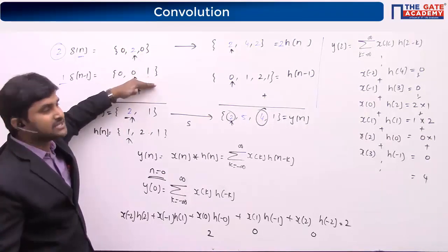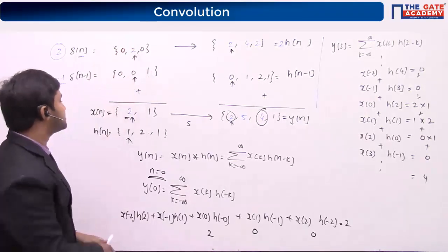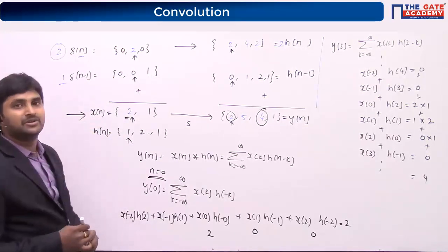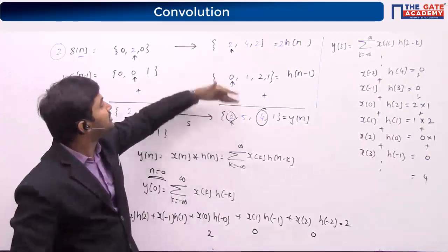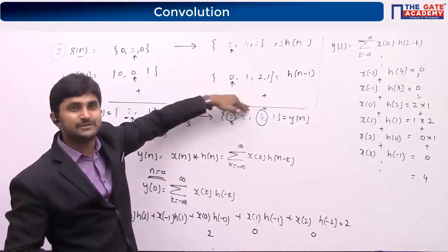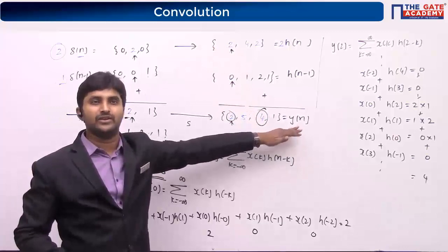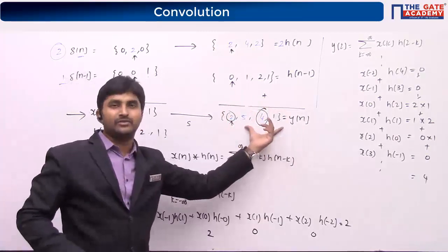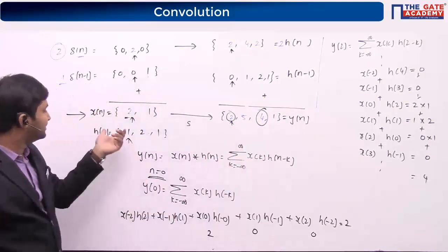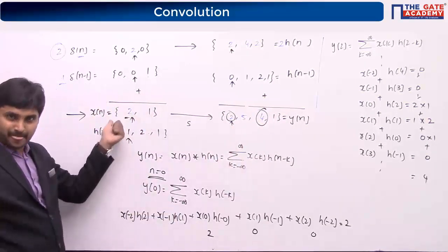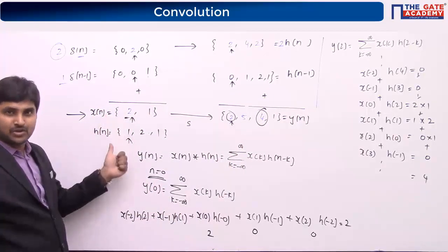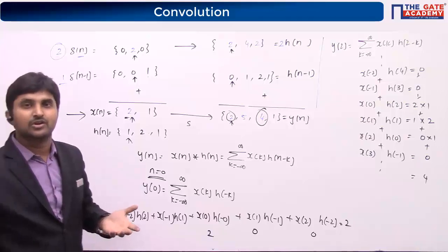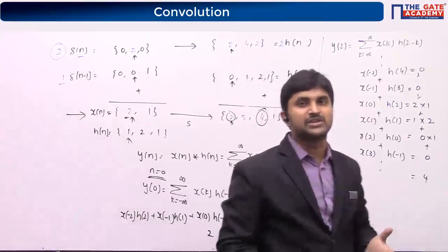Impulse, delayed impulse. So when you add them together, this is the overall input that I have applied. So when I calculate the overall output, it should be the addition of the impulse responses. This is what we are calling y of n. So to get this y of n, what we are basically doing is using these two only, every time. The operation that we are performing between both of them is what we are calling convolution.